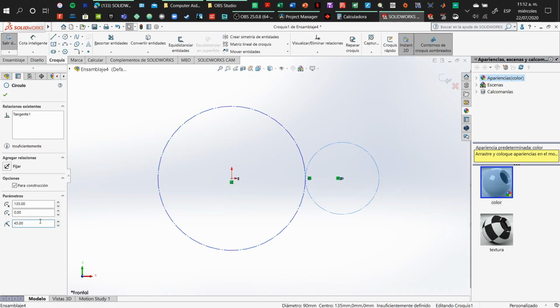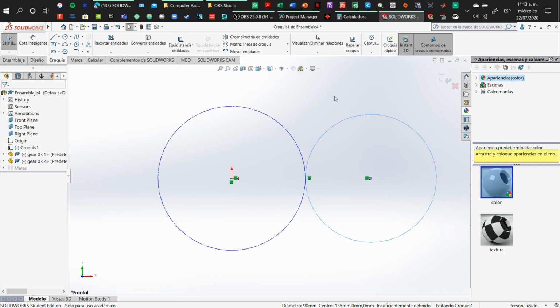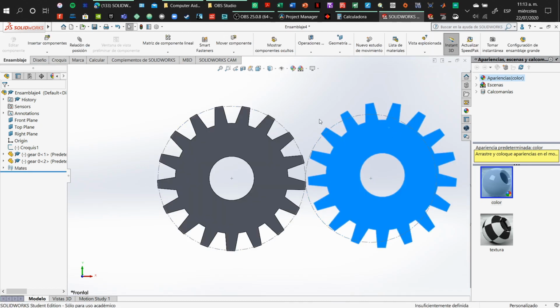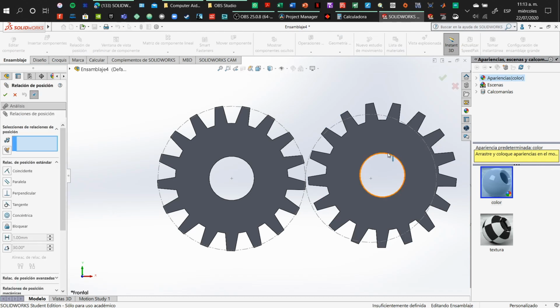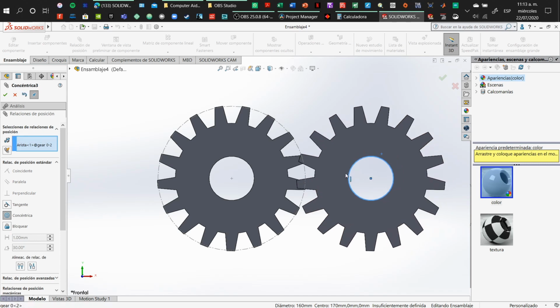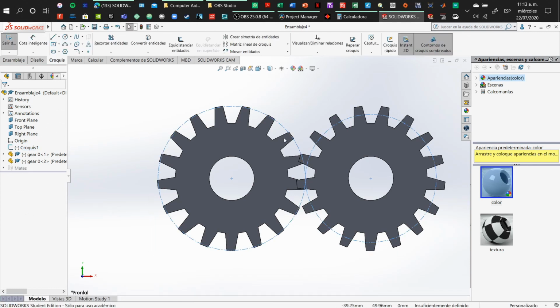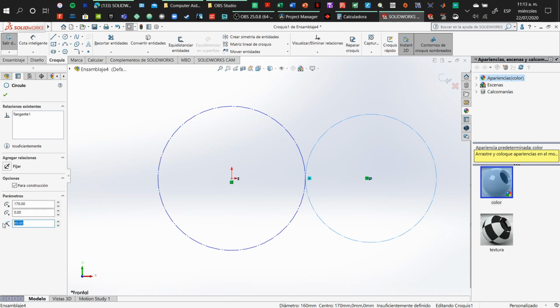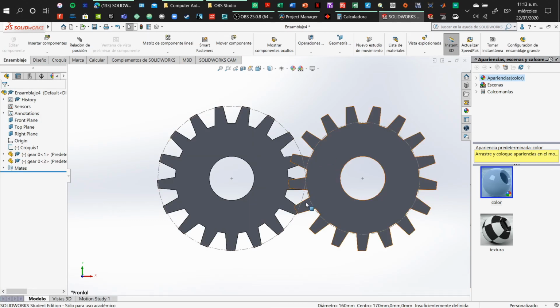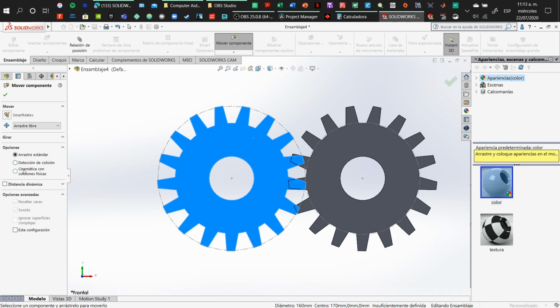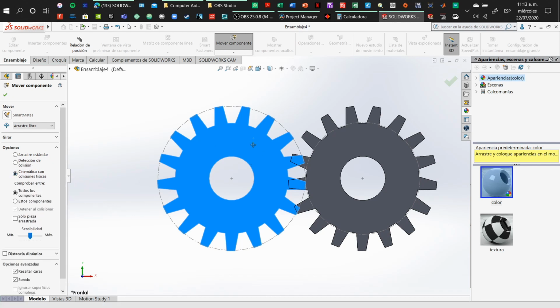So when we're fixing this value, we can make it slightly smaller than the first one, because we want the spur gear to intercept that gear. So we can make now the concentric relationship, and as you can see, they are getting the interference, but it is too little. So I will change the value again. So I think it will be enough, but now we can see it's too much. So I will change it again, and that way we can make a better movement study.